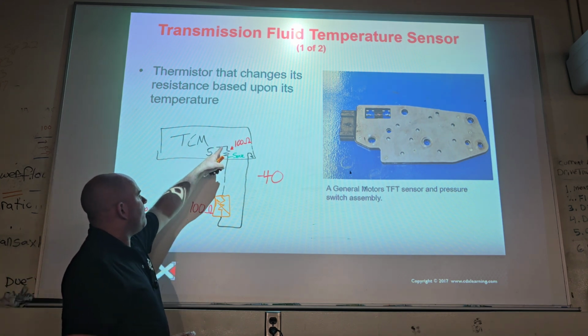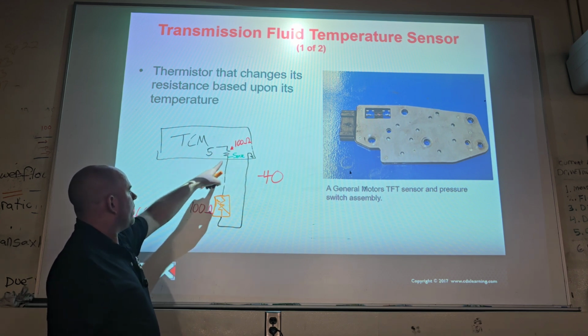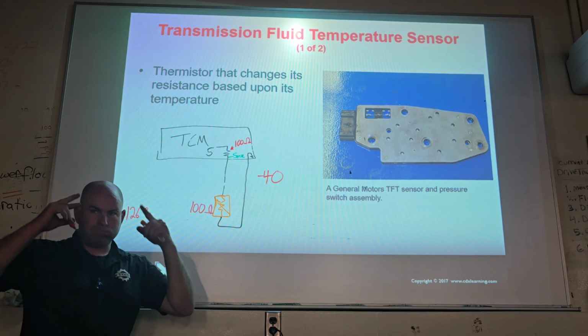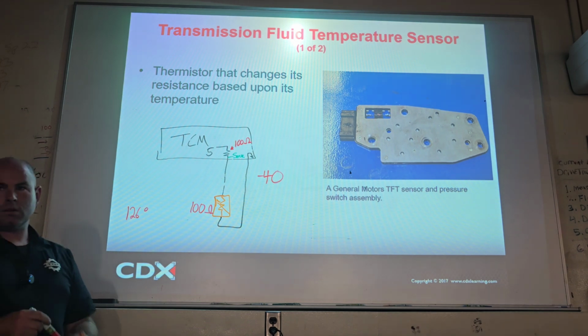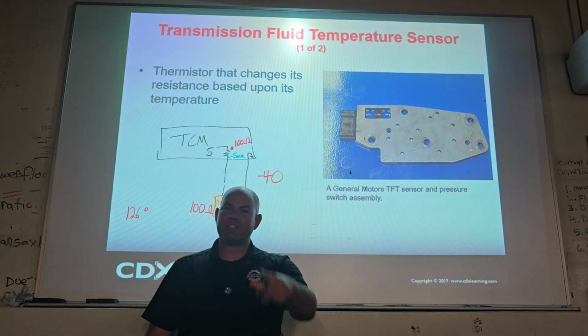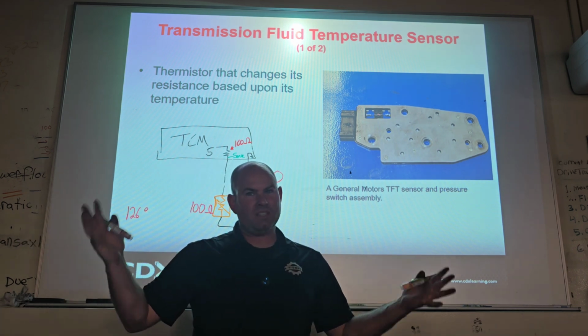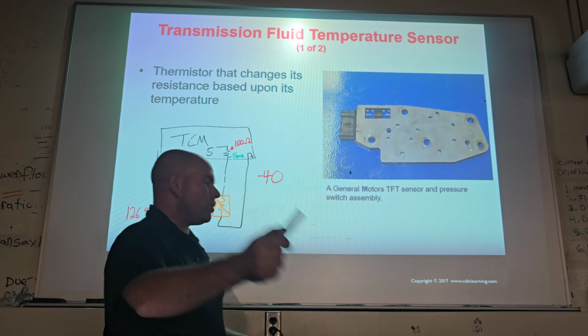If we had 5 volts coming in, a 100 ohm resistor here, and a 100 ohm resistor here, what is it measuring on the sense wire? Want me to break it down? 2.5 is right. You paid attention in AC, didn't you? We covered this in AC. This is review. How do you know it?